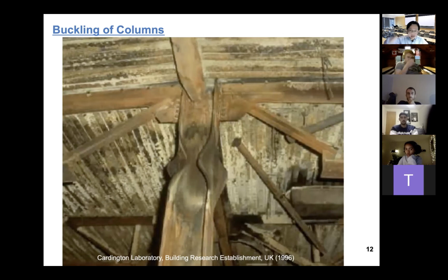That means the slabs can actually tilt. And when the slabs tilt, the beam underneath will usually just be twisted. When there's an axial force acting on beams, that will result in what we call torsional buckling. In this case, it is the torsional buckling mode for columns. That is not that common, but for beams, that's very common.